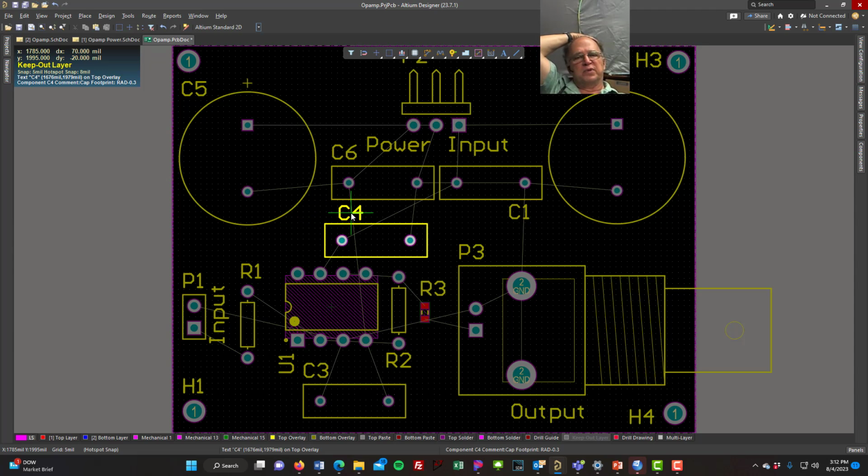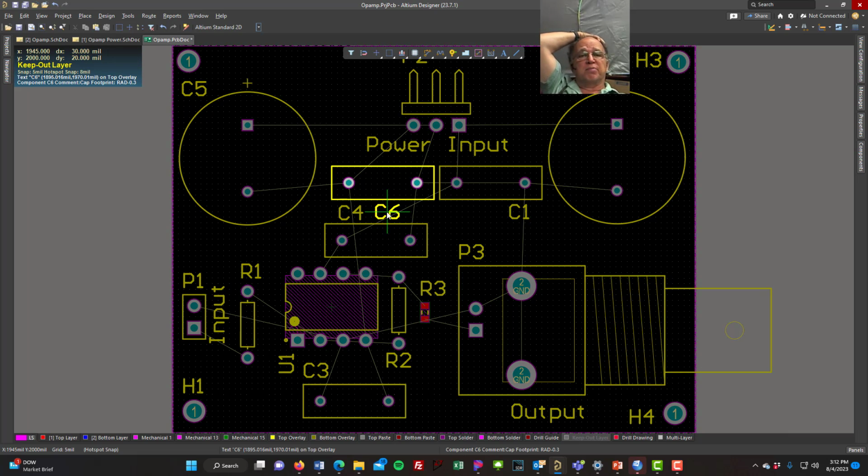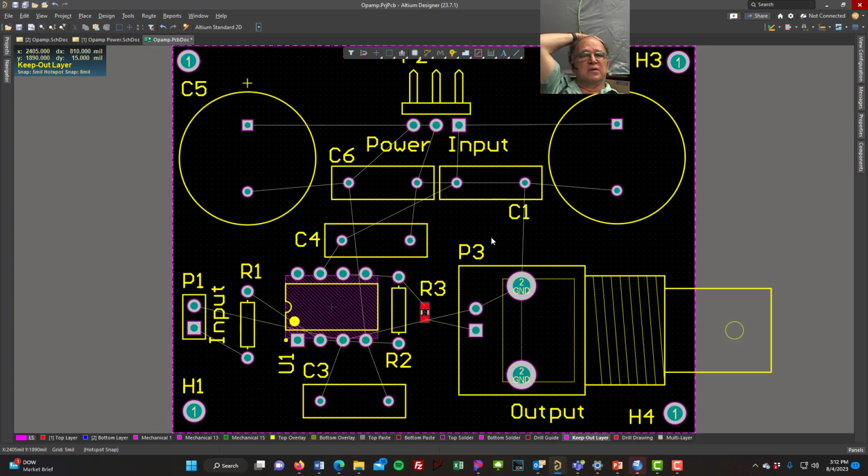You can see that if I put this here and this one here, I can't really tell which cap is which. Now when I grab the designator, you'll see the cap is a little bit brighter. I can tell here, but if I mass produce this, I wouldn't be able to tell. So I'm trying to be smart about placing my designator so I can tell where things are going. All right, this looks pretty good. Let's leave this here and we'll have some more to work on the next video.